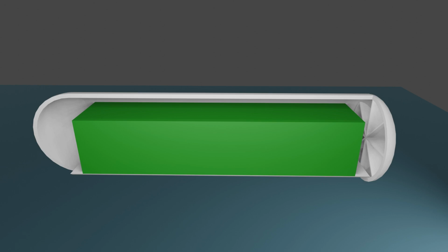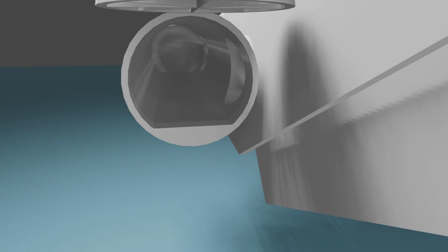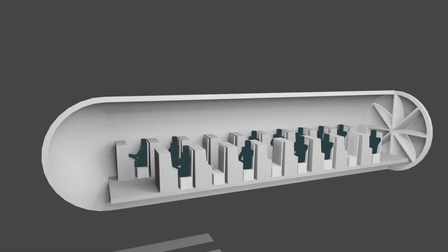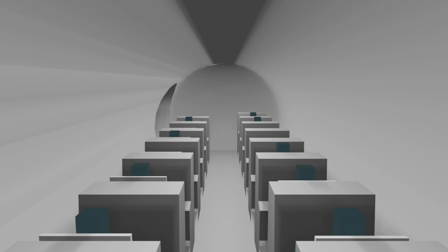Additionally, for the military, there would be cross tubes between the main tubes. This would enable pallets or platforms with workstations to be installed, and then personnel can man those workstations, and the aircraft can be used for electronic warfare or other missions. The fact that it's divided into 3 separate rooms does make it somewhat less efficient, but it can probably still be made to work. Antennas can be mounted in pods on the outside of the aircraft.